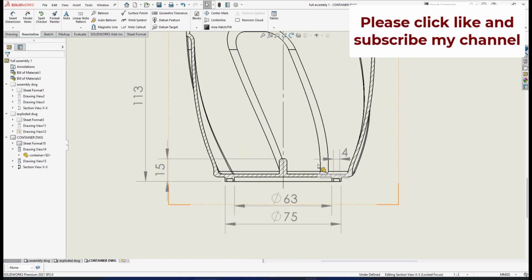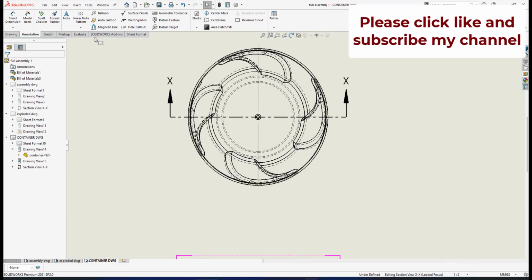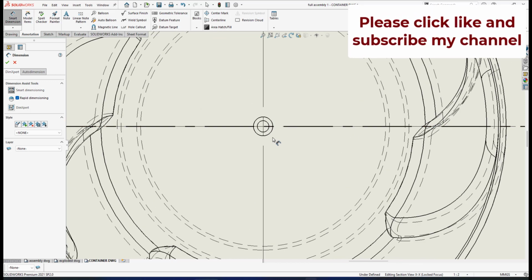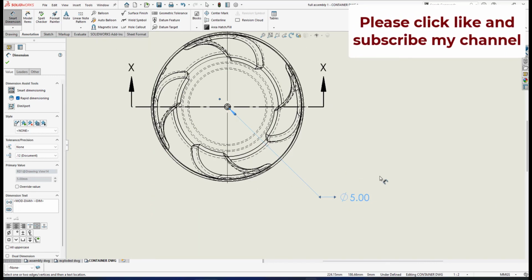So the other dimension will be the diameter of the shaft. Then I can put a dimension here. This is a top view, so I can click at this circle. This is the shaft. We have the icon here. I can go to this quadrant. Then I click OK. SolidWorks will put the dimension at this position.